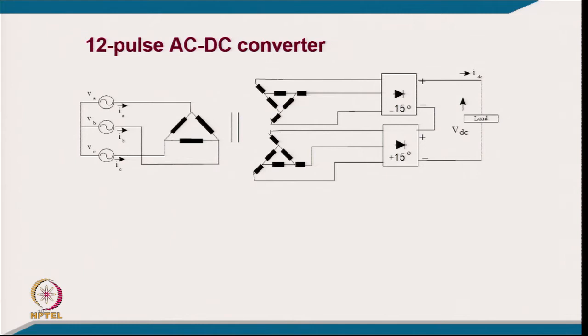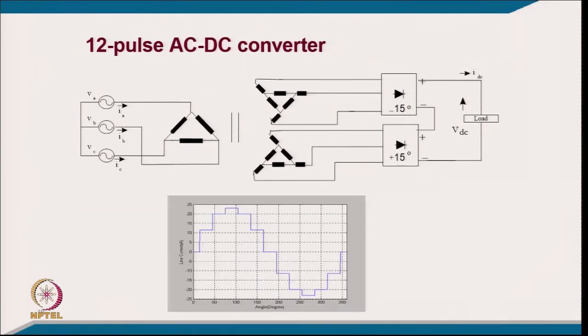So, here we are getting 15 degrees, you can call it leading compared to the input voltage, and here we are getting 15 degrees lagging with respect to the input voltage because of the extended delta. So, the number of turns we calculate accordingly from the geometrical relation to get the phase shift, but you can still have equal voltage, their voltage will be on the same circle.